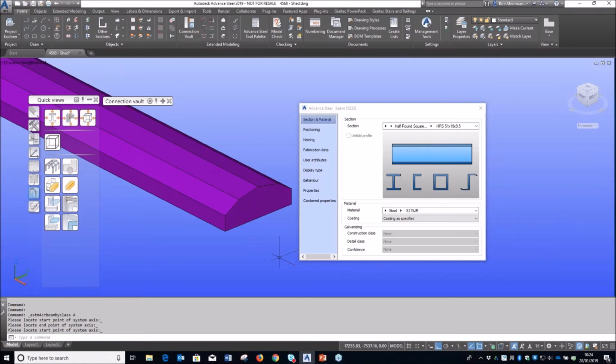Now this is all well and good that we've added it in this way, but it's not been added into the railing macro. So at the moment, the railing macro won't work with these. The last little bit I'm going to show you today is how you can add that to the railing macro. We're going to start customizing some tables, copying some data and creating some new elements.